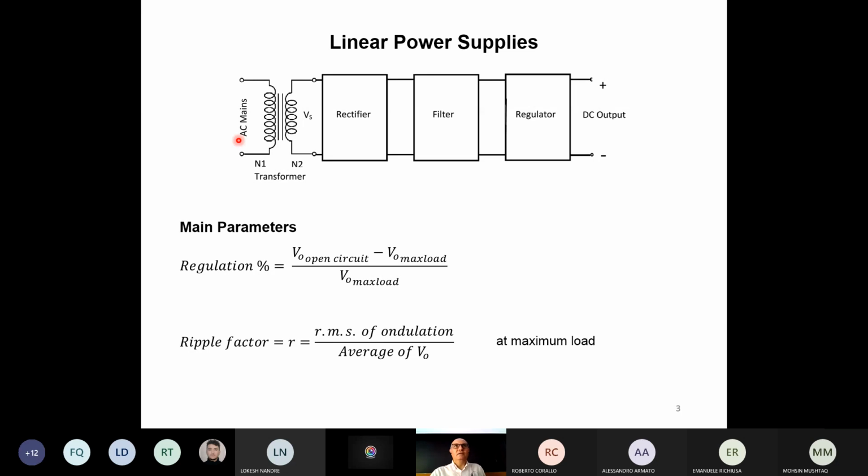When I say 230 volts, I mean the effective voltage, tensione efficace. Effective voltage means that the real peak value is 1.4 times higher. If you remember, the relationship for a sinusoidal voltage between the peak voltage and the effective voltage, tensione efficace in Italian, is square root of 2, radice di 2. So you have to divide the peak voltage by 1.4, and you get the effective voltage.